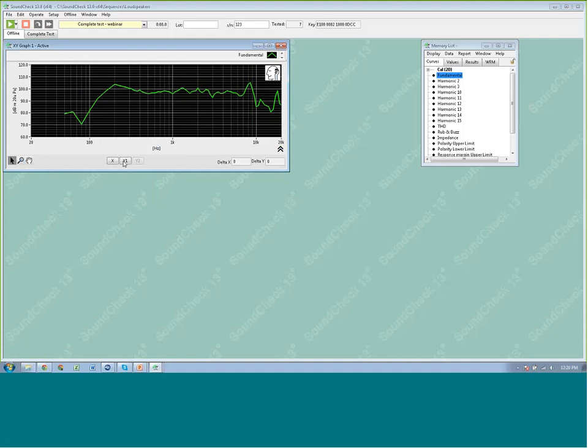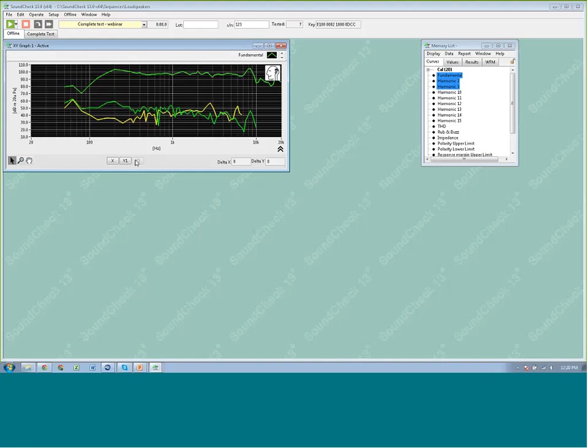If I wanted to re-auto scale, I have these two buttons here. So for example, if I added some more data to my graph, now I have some new data here, but I can't see it because it's off my graph. If I wanted to just re-auto scale the Y-axis, I could re-enable auto scaling by right-clicking here. But if I just want to do a one-time auto scale, I can click the Y button down here. And now it re-auto scales to include all of my data.